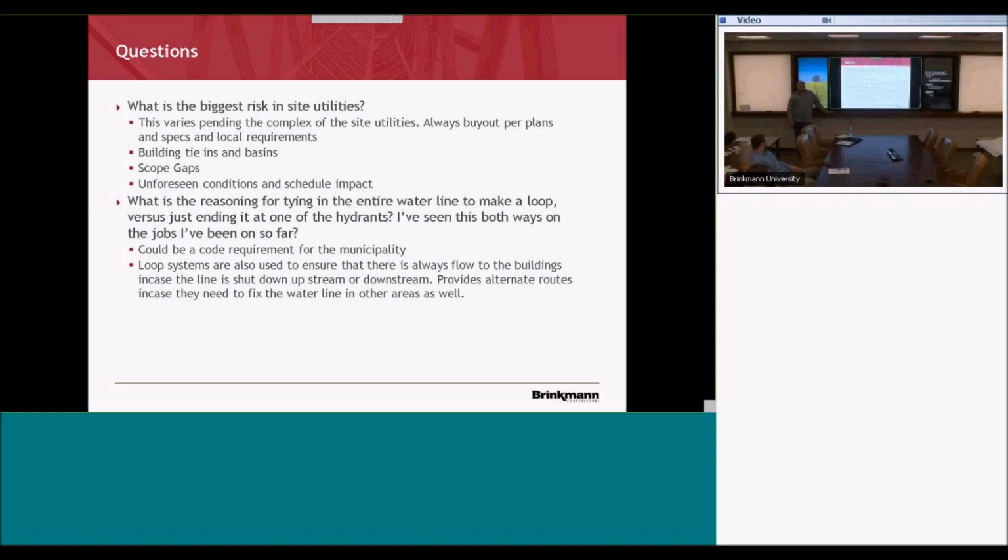And then another one is pre-existing electric service poles. If they are just barely the 10-foot minimum away from your building corner, and it looks good at the ground, but no one looks up to see that you've got 3 feet of arm sticking off the pole holding the lines, and then your roof truss tails come out 3 feet, then you're down to 4 feet of distance.